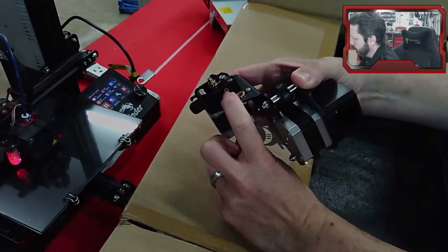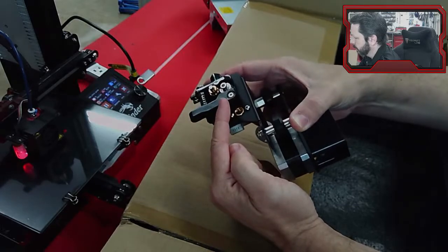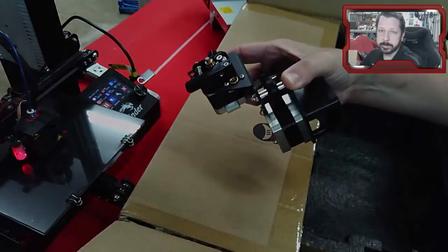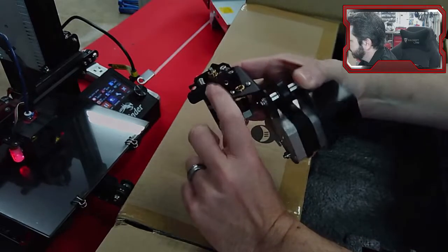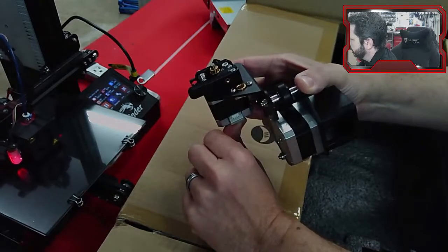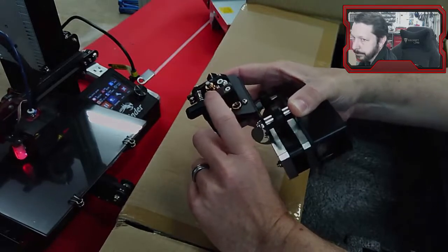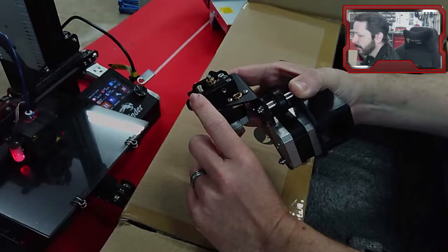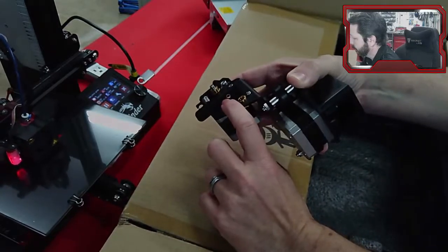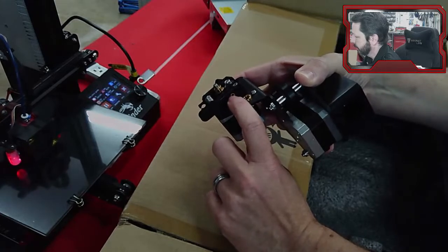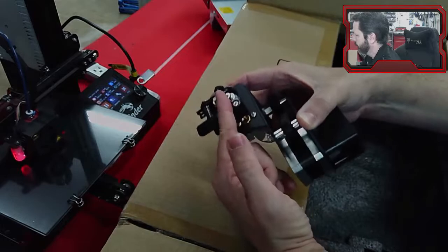If that metal insert is not there, the filament is going to cut a groove all the way through this thing eventually, and you'll have binding problems. So if yours has just a plastic piece right here, then at some point you're going to want to replace this. They're $10 or $15, and it'll be a while before you need to replace it. But now they've started shipping most of them with this little metal insert that keeps the filament from cutting away this groove in the thing.